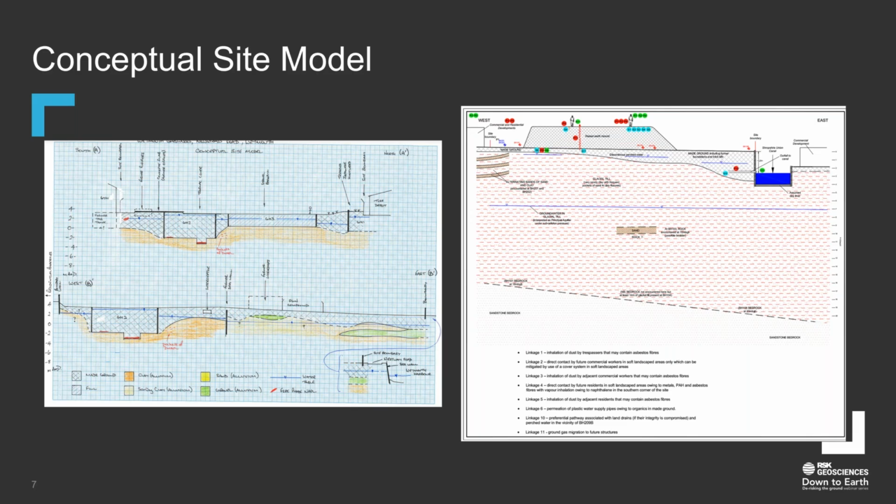And yes, planning is all about questions. What to sample? Do you need samples of soil? Do you need samples of groundwater, gas, vapors, or even potentially free product or NAPL? What locations do you want to sample? Is there a targeted approach? For example, you're targeting specific buried obstructions that you want to find, or is it non-targeted? You don't have much information about the previous history, so you're just going to do a grid across the site.